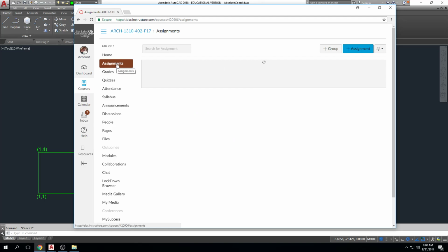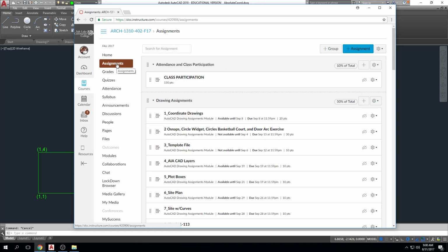And let me just tell you guys, yep. Sorry, I keep doing that, but it goes sideways. It's because your dynamic input's on. Yep. I tried turning it off too. It's this one, right? Nope. Dynamic input. So you already have your dynamic input turned on. Oh, this one. It's this one right here. Oh, you have to turn it back on. Oh, there you go. Turn that off. There you go. Delete that line and start over. Okay.